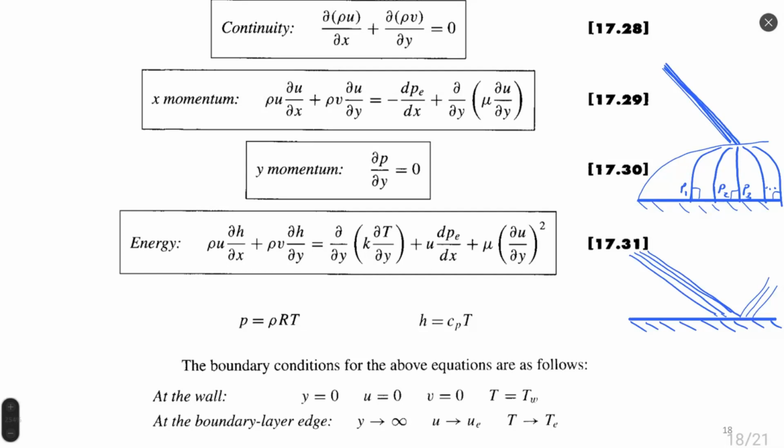So these lines are not perpendicular to the wall. So once we see this figure, we understand that the boundary layer was not simulated. Once we see figure on the top where pressure lines change direction to normal with respect to the wall, we understand that this simulation was viscous. Okay, viscous and inviscid.